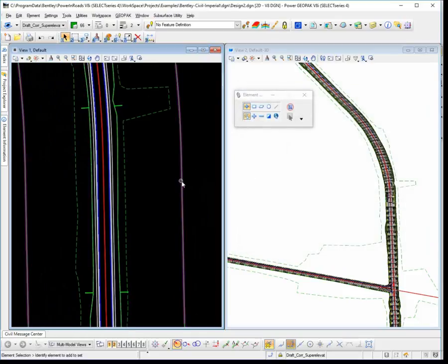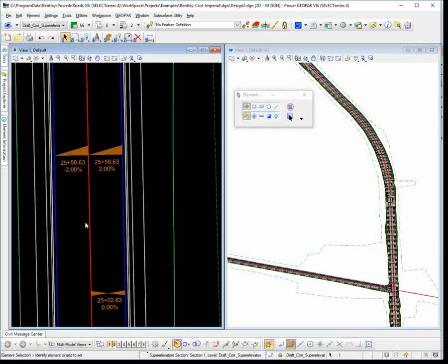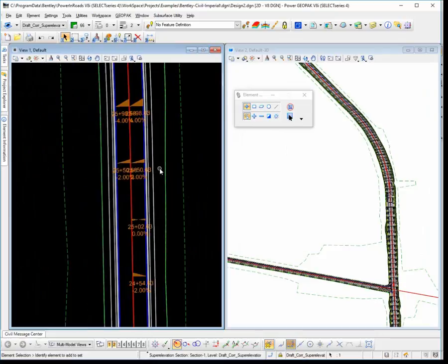And then when you select your superelevation object, you can still go in here and graphically change things. But the rendering of those lane objects does take quite a bit of horsepower. So on large jobs with superelevation, it's better to not have that fill on, and you will see increases in your processing speeds.